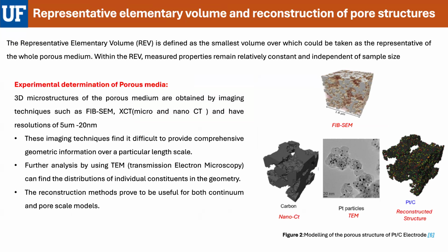In order to experimentally determine the porous media structure and effectively develop the pore-scale models, we use 3D scanning techniques such as focused ion beam SEM, X-ray computed tomography, and other analysis like transmission electron microscopy to develop efficient porous structures. So how is this done? We are going to take an example of modeling pore-scale models of a platinum on carbon electrode.